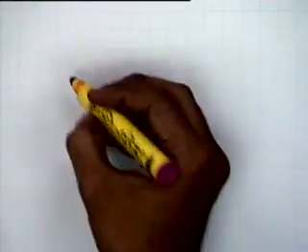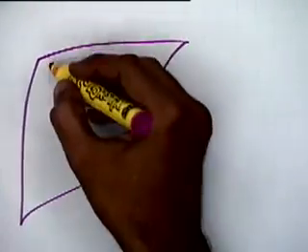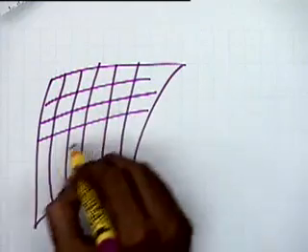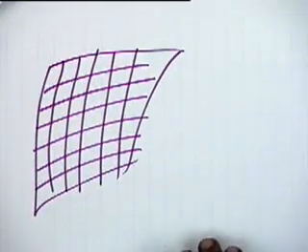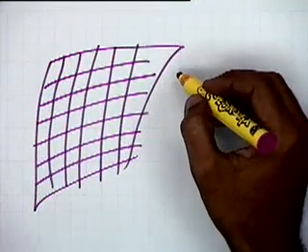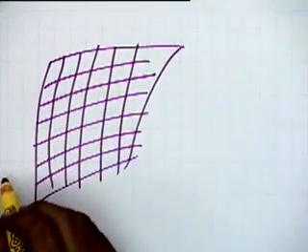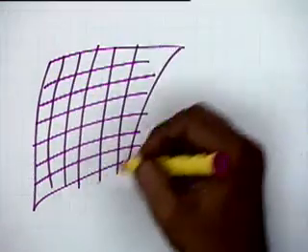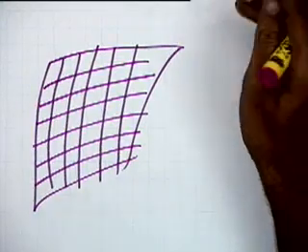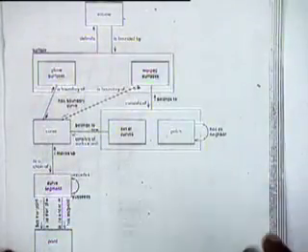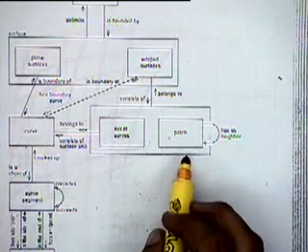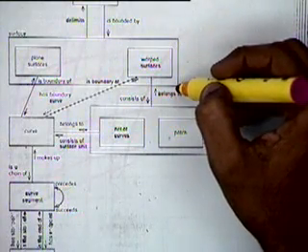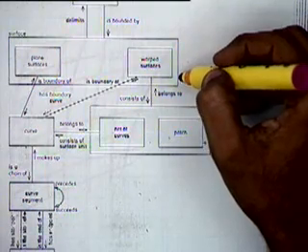For instance, if we take a set of curves like this, we say this is a family of curves, one set of maybe cubic curves in one direction, another set of cubic curves in the second direction, and this defines a surface patch. So we can have a network of curves, or we can have patches which can define a warped surface, or which can define a three-dimensional surface.